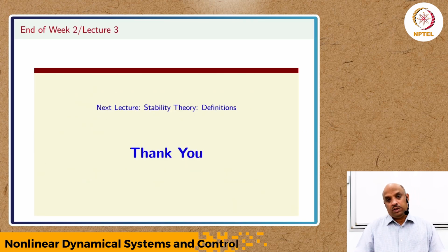In the context of controls, we don't want anything going unbounded, we want perfectly bounded, and in most of the cases we'll have a target solution to reach, and that's trying to reach an equilibrium point. Suppose the natural behavior of something like a van der Pol system is its limit cycle. Can we put in a feedback control so that the limit cycle behavior is modified to a case where we have equilibrium points?